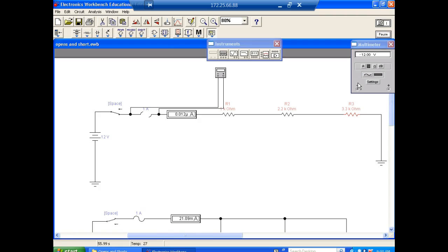So that black lead is not a circuit common. The black lead is a common to the meter, right? You understand that? So in a DC circuit, if you hook them up backwards, you just get the opposite polarity from what you expect. That's on digital. On analog, very important. You can mess up your pointer. Then you bend that little pointer, and it's so fine anyway. If y'all have ever seen one, it's a really narrow thing. They put an end stop and it'll peg up against that. If it bends, then all your readings would be off after that. It's a dead giveaway you got something wrong. Okay.